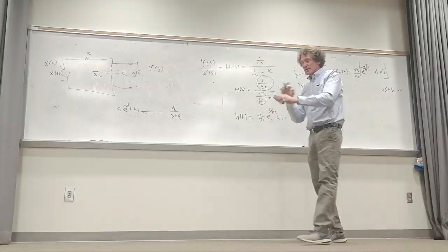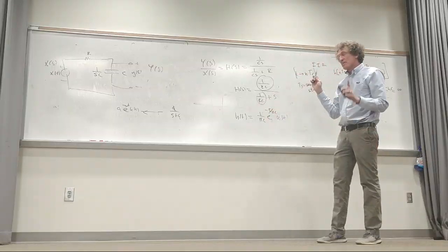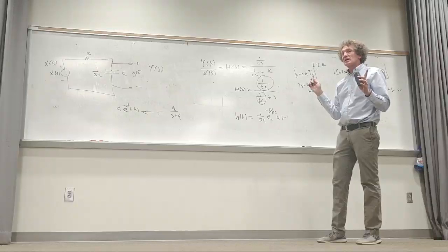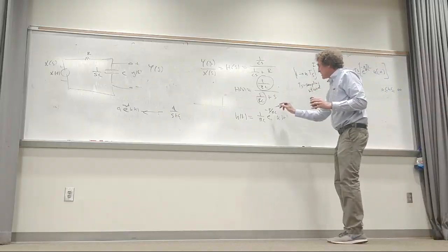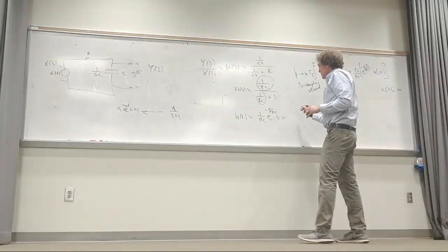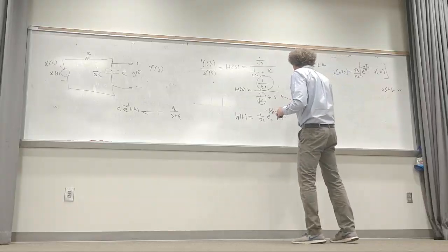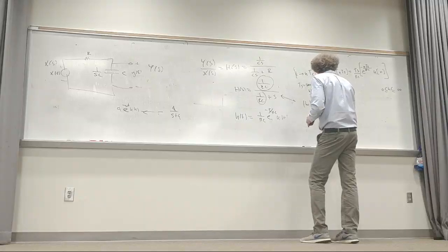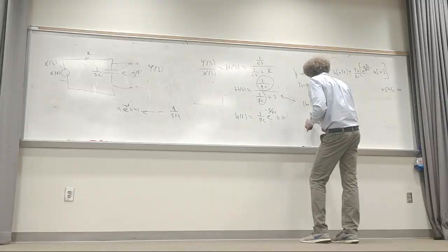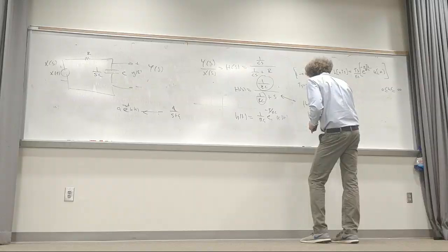Yeah, I mean, I'm not going to go into too much more about these filters. But when you do it in the sample domain, right here where you have nTS, now for this filter right here, in the frequency domain, it would be magnitude of omega equals 1 over RC, or simply magnitude of F is 1 over 2 pi RC.